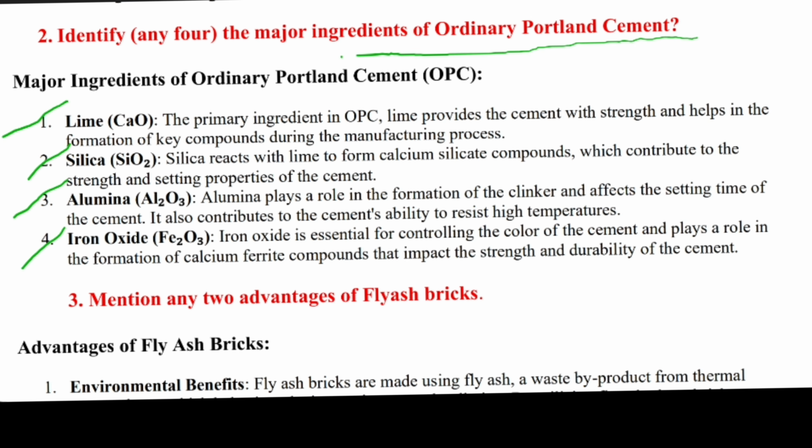Coming to silica, silica reacts with the lime already present in the cement. Silica reacts with the lime and forms a calcium silicate compound, and it will give good setting time and strength. It gives the good strength and setting property of the cement.